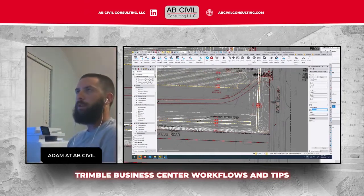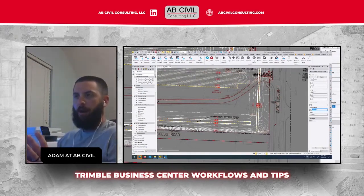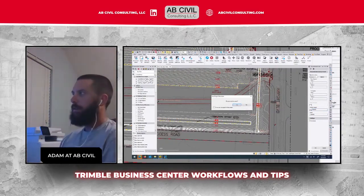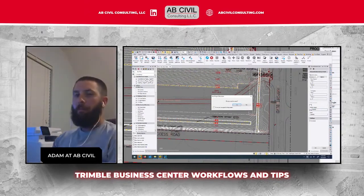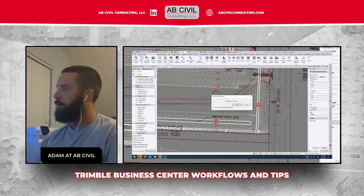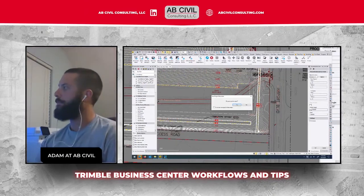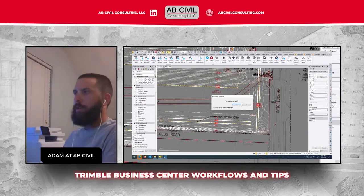The grading was designed in AutoCAD alongside the building plan, so everything was 90 degrees to the foundation of the building. None of it was in a coordinate system, but they gave a lot of good control points, and I picked 2 of the primary control, and I did exactly what I just went over and rotated all my line work right into my coordinate system. You'd only need 2 points to do that. Hopefully that answered your question.